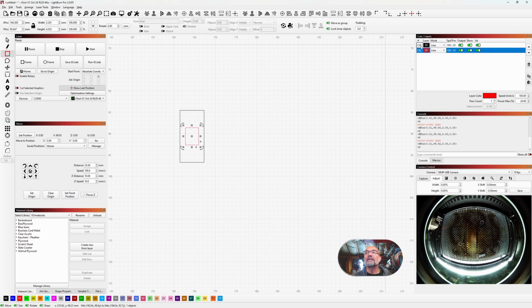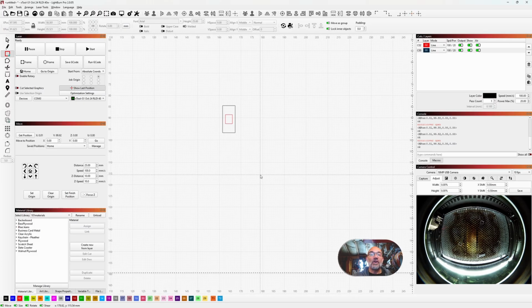I could drag like that and it goes up, or you can use these little arrow keys here. You go like that. So I want this red on top. So what happens now? In the process of the laser, it would then cut the red out if I set the power and everything properly there, and then the same thing with the black. Here's a hotkey to know: Alt-P.